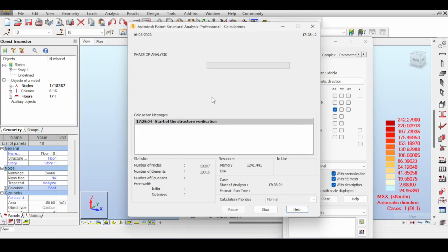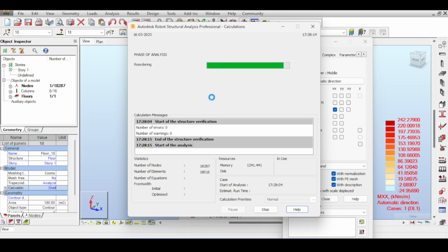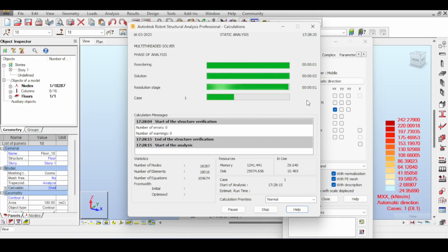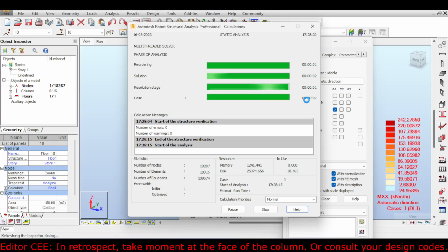So I think I've talked about this before. And to try to explain what I talked about before, I said that if you have a finite element mesh and you have a moment on top of a column, then you should not basically take the top of the column tip as your moment. Maybe you want to just move away 5 centimeters or something just to get reasonable results.